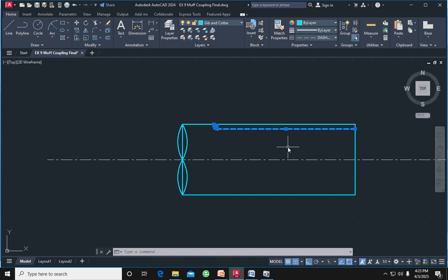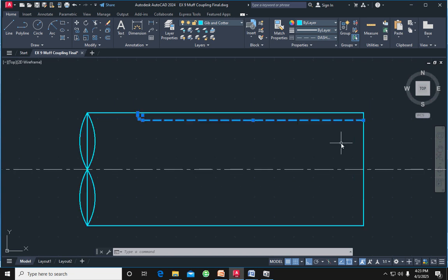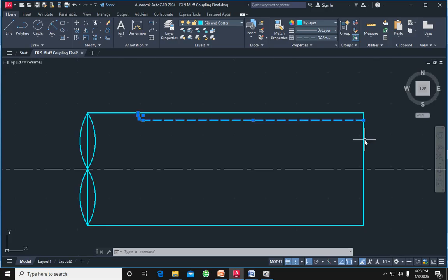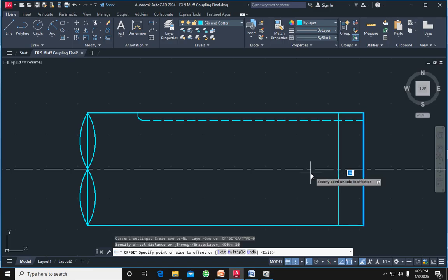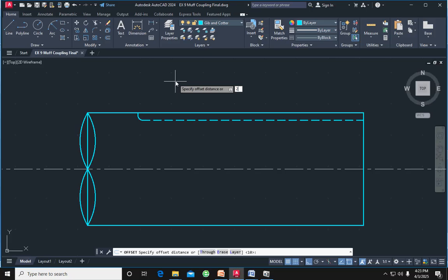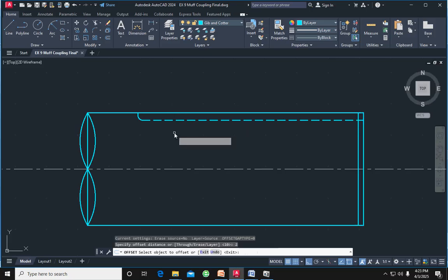Next we have to take a keyway on the outside. So in this case, we take a keyway from inside. So we select this point, take an offset, select this point, take an offset, and on the inner side we take 10 mm inside. Okay, 10 mm inside is too large, so take an offset. We provide distance 2. Okay, 2 mm distance.